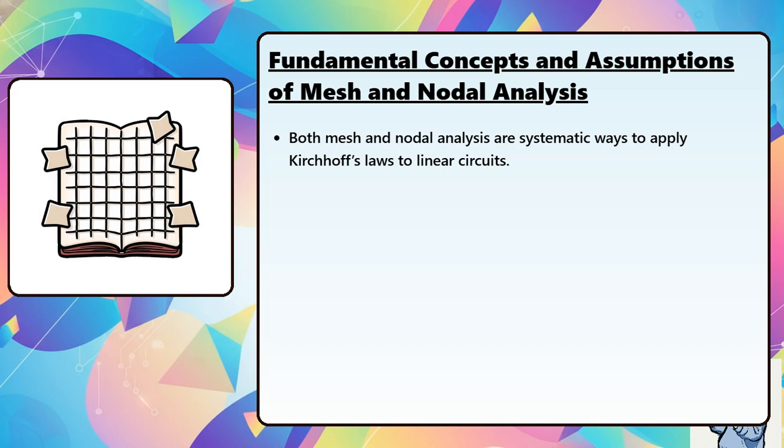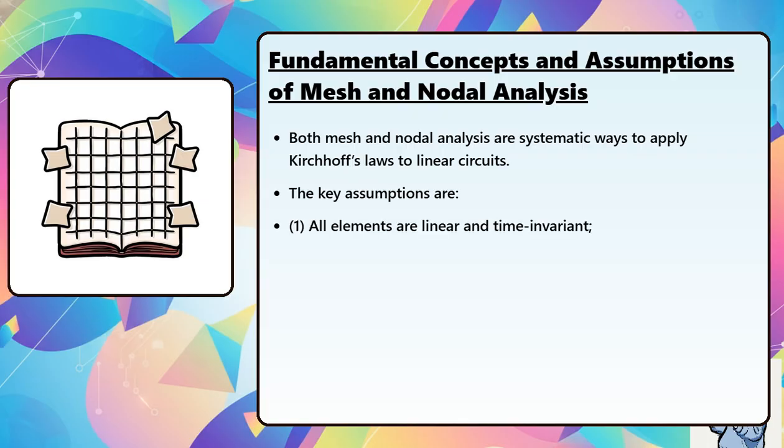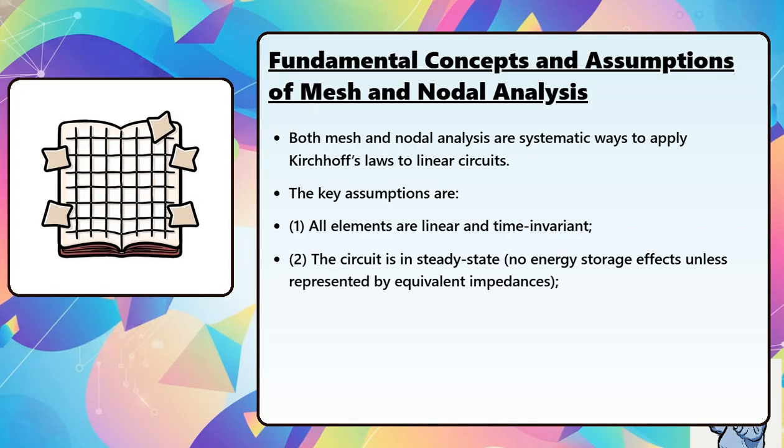Both mesh and nodal analysis are systematic ways to apply Kirchhoff's laws to linear circuits. The key assumptions are: all elements are linear and time invariant. The circuit is in steady state, with no energy storage effects unless represented by equivalent impedances. The network is planar for mesh analysis, with no crossing branches.